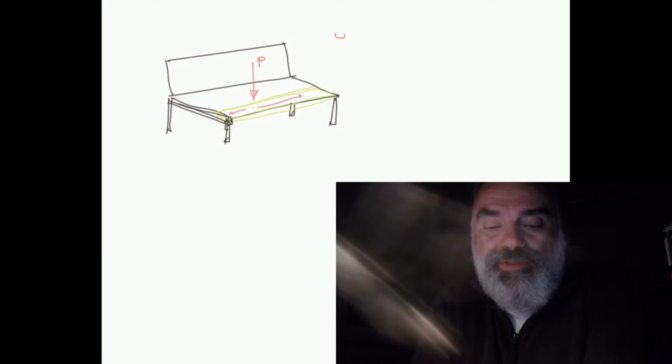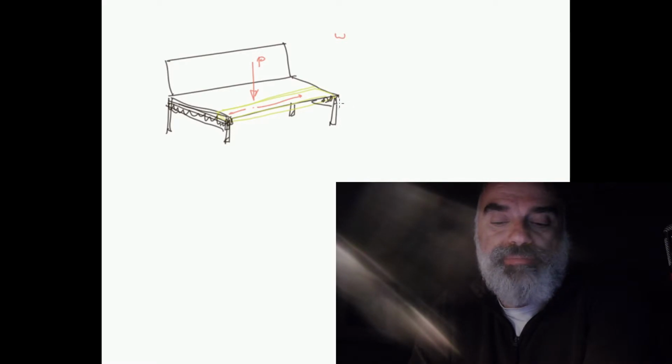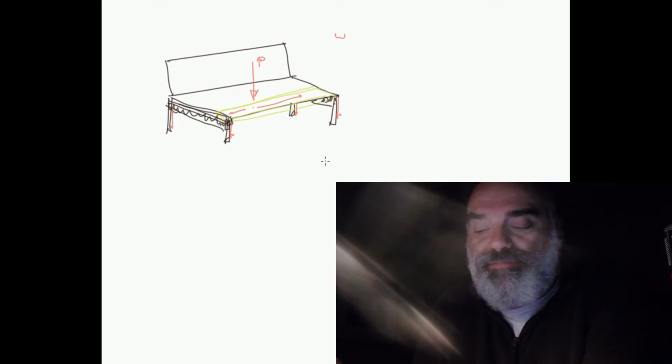So we've got a beam that acts here, which picks up all these planks, and one at this end. So we'll have a plank that's supported essentially between these two beams, and those beams carry the load down into the legs of the park bench. So those loads come down each of these four legs in this case to the ground where it's supported.